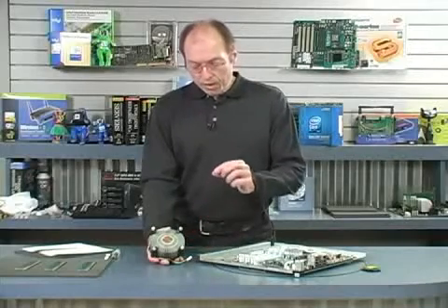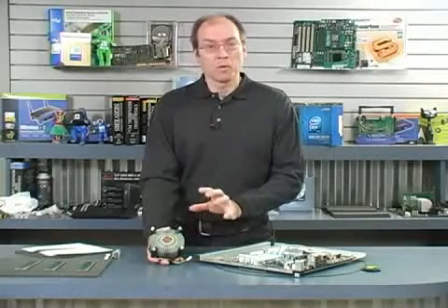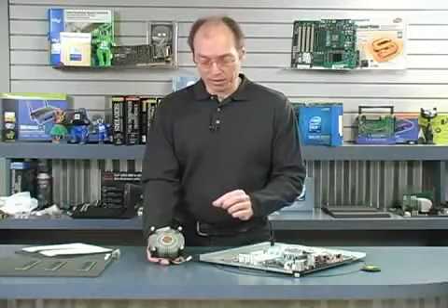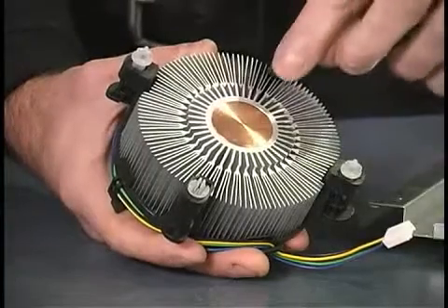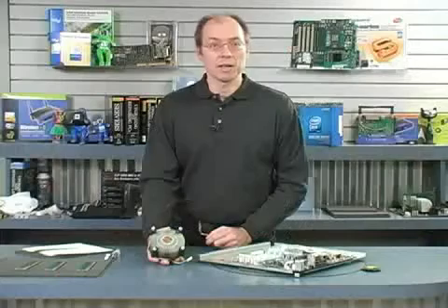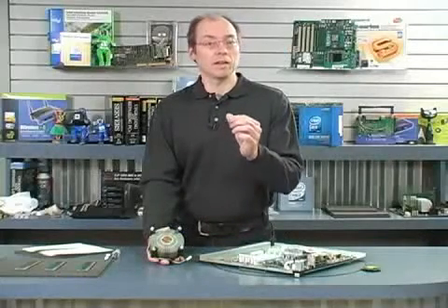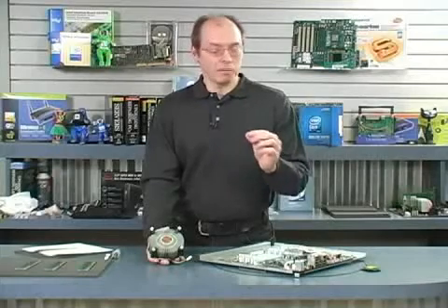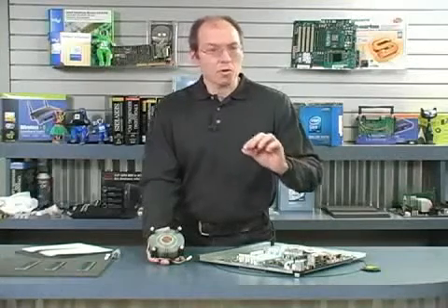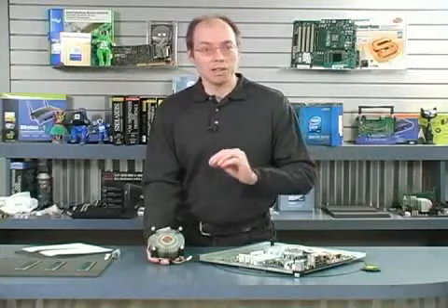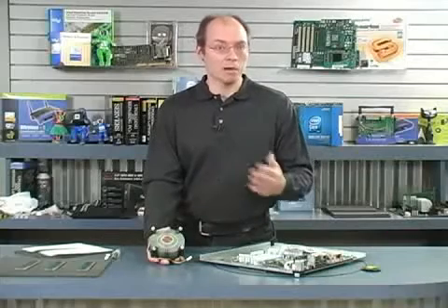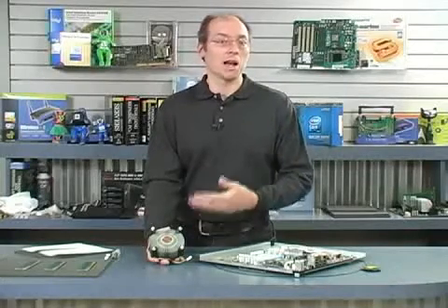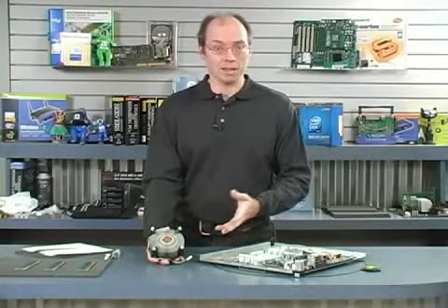Now, in addition to talking about that, we need to talk about what's called the thermal interface material. That's the material that basically has to go between the processor and the heatsink. The thermal interface material is basically a grease or a wax type substance that makes sure that there are no little tiny air gaps, so that the maximum amount of heat is transferred from the top of the processor to the heatsink. If you don't use the thermal interface material, you're compromising the performance of the heatsink dramatically.